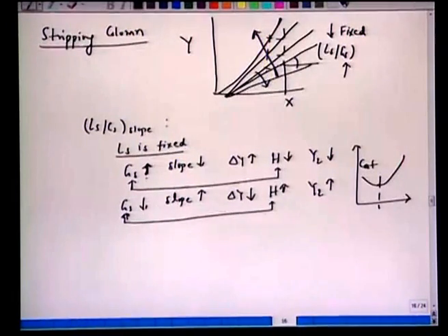Now we restrict our discussion to the mass transfer. In some course in design, maybe third or fourth year level, you are going to address this aspect. You will make some cost balance, etc. Okay. So when we approach the equilibrium curve, there is a risk of this operating line making a tangent with the equilibrium curve, where we have what we call the pinch.